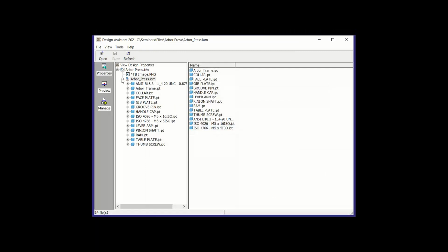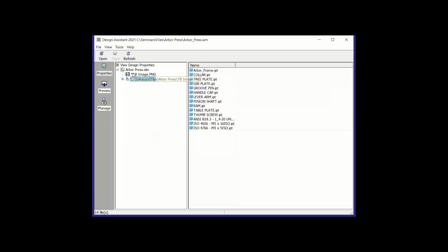And as you can see throughout the couple of files that I've brought up here, if you open any IDW or DWG file, the first thing it will tell you, on a little plus sign, if you collapse it, will tell you any associated files. If there was a spreadsheet, this happens to be a title block, which has a title block image linked to it. So that's a quick way you can see what other file dependencies are in the associated Inventor file.